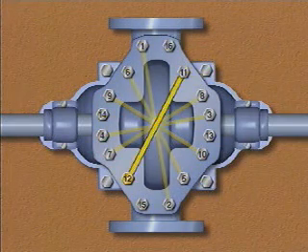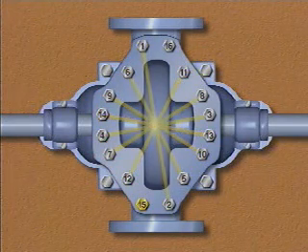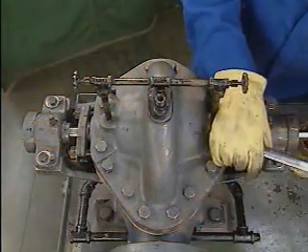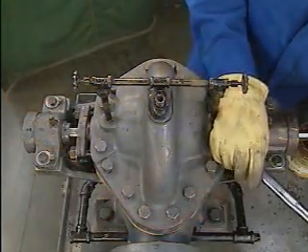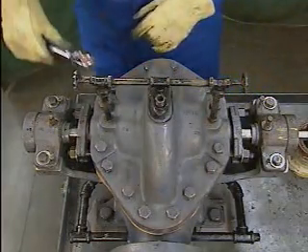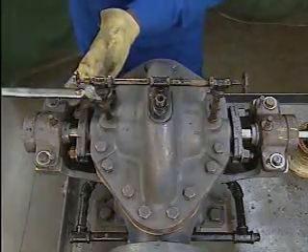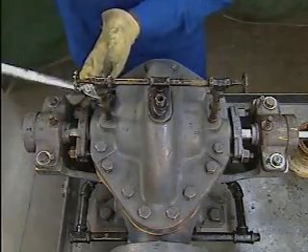The mechanic follows the pattern, crossing back and forth until all the bolts are tightened to the required torque value. He will repeat this pattern several times, gradually increasing the tightening pressure in several stages. If this tightening process is not followed, the sealing surfaces could warp, or the gasket could be improperly compressed.